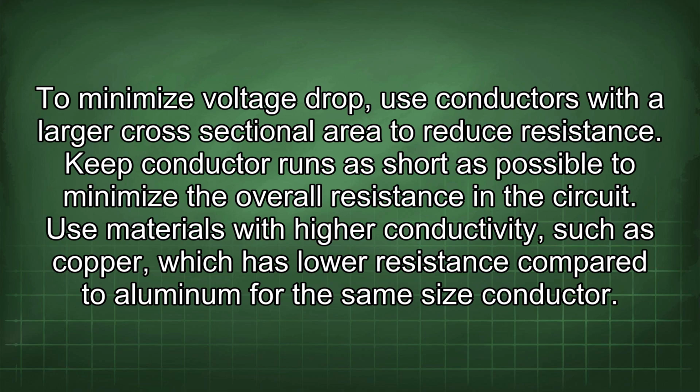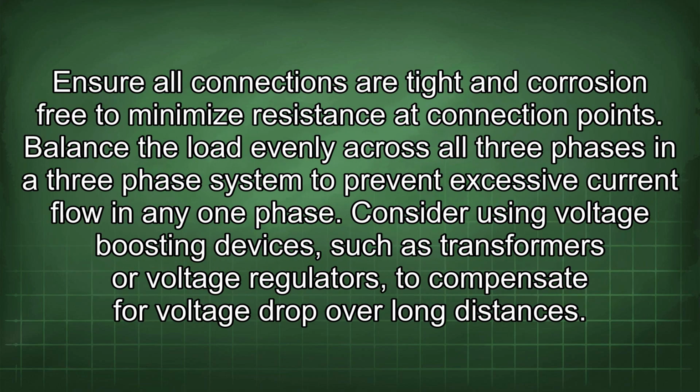Keep conductor runs as short as possible to minimize the overall resistance in the circuit. Use materials with higher conductivity such as copper, which has lower resistance compared to aluminum for the same size conductor. Ensure all connections are tight and corrosion-free to minimize resistance at connection points.